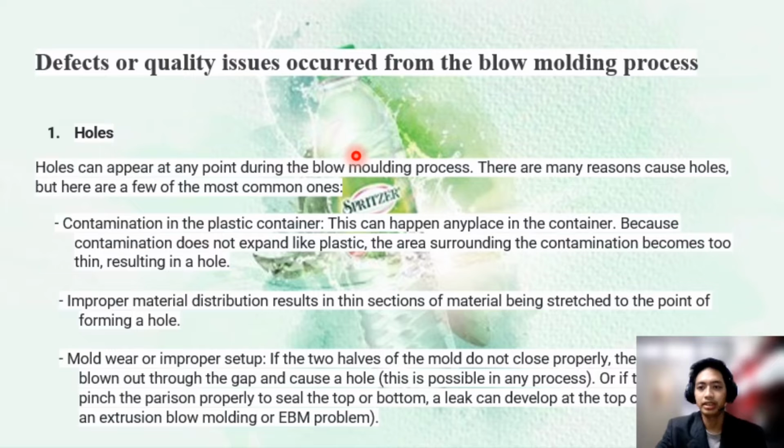There are many reasons that cause a hole, but there are a few of the most common ones. There are 3 common ones here. The first one is contamination in the plastic container. This can happen anytime or any place in the container because the contamination does not expand like plastic. The area surrounding the contamination becomes too thin and it will result in a hole in the container.